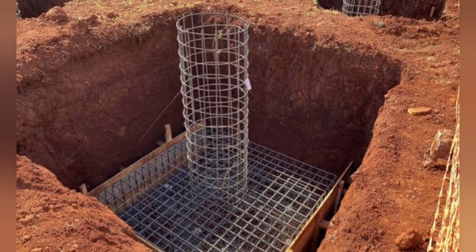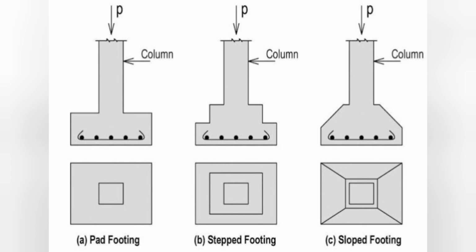If the hard strata is not available, the piles transfer load via skin friction mechanism in which friction is developed between soil and pile surface. Raft foundations can be combined with piles when more number of piles are closely spaced and the whole raft acts as a big pile cap.